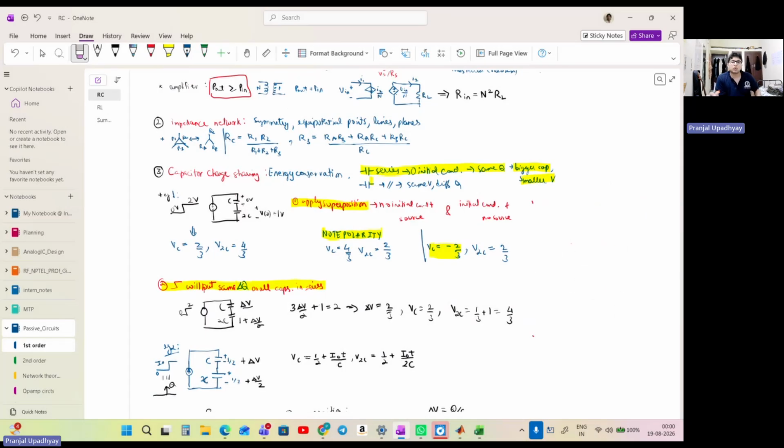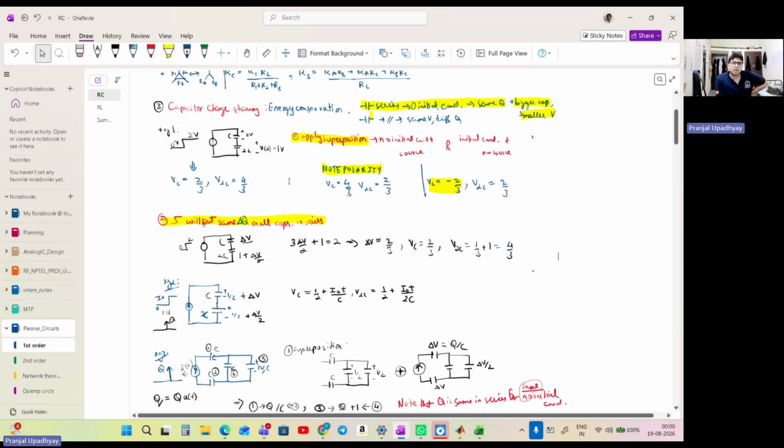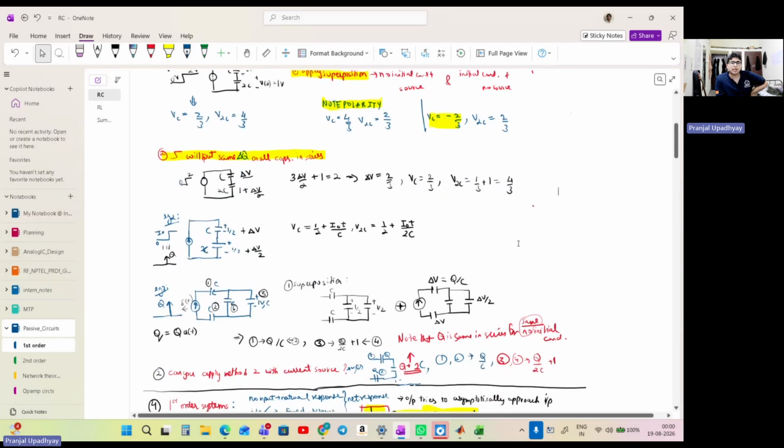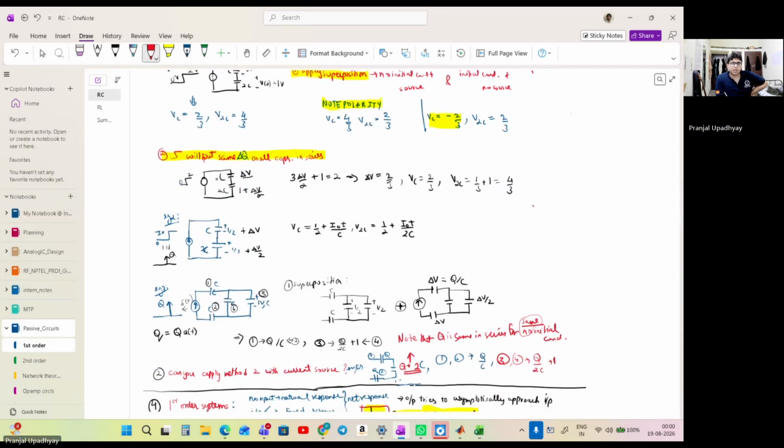That's why it took me a bit more time, but we can actually do this quite quickly by thinking it in our head also, right? Another way, and this is a way that I personally like also. And what is that way? As I mentioned before, whatever voltage step happened, it will induce the same charge across the capacitors, right? Like whatever the voltage change, the capacitors in series will experience the same charge. If they are experiencing the same charge, from that alone we can intuitively comment on the change of voltage they'll experience, right?